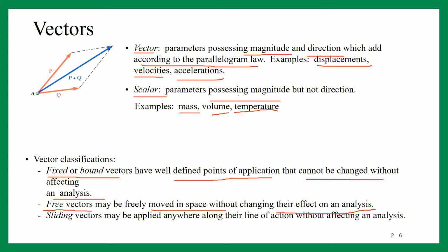Means if you move the free vector, then the analysis will remain same because they are free vectors. So they do not have any effect on analysis. Means you can change their position and the analysis will not change. Then third is the sliding vector. So it may be applied anywhere along their line of action. In the previous video, we have discussed about